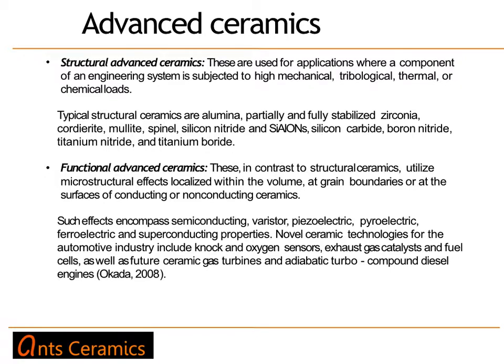So we have seen that advanced ceramics are divided into two categories: structural advanced ceramics and electroceramics, or functional advanced ceramics. Structural advanced ceramics are used for applications where a component or engineering system is subjected to very high mechanical, tribological, thermal or chemical loads. These include wear resistant ceramics like 92% alumina or 99% alumina, partially or fully stabilized zirconia, cordierite, mullite, different kinds of spinels, silicon nitride, silicon carbide, boron nitride, boron carbide, titanium nitride, titanium carbide, titanium boride, etc.